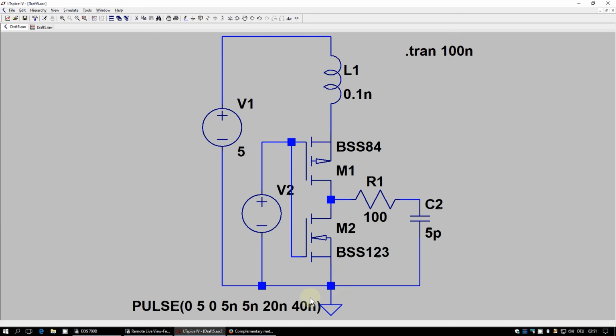How do you get a perfect ground? Well, if you're using a ground plane in your PCB, that's the next best thing to an ideal ground. Otherwise, if you have extra PCB traces for your ground, you would also have to insert an inductor here to ground, which makes things still worse. But let's not get too complicated.